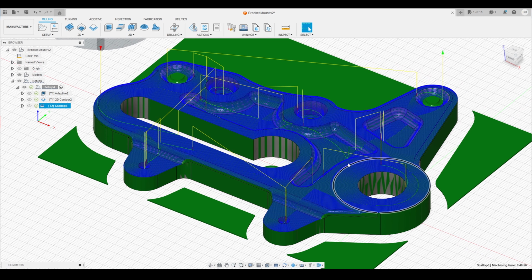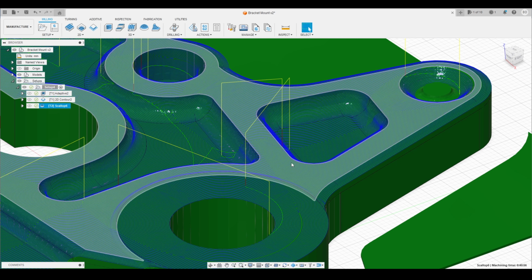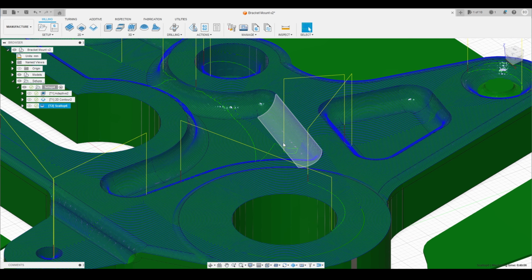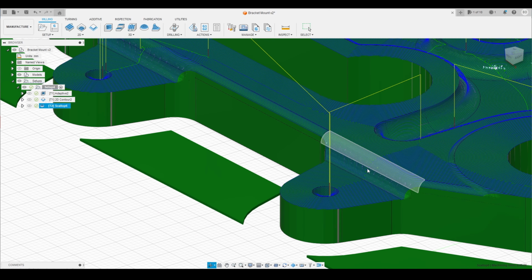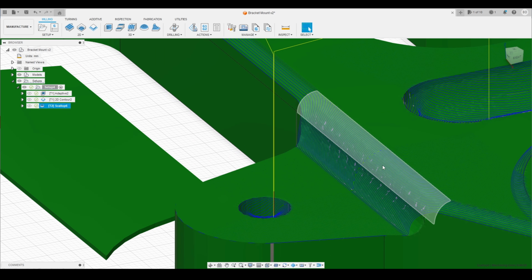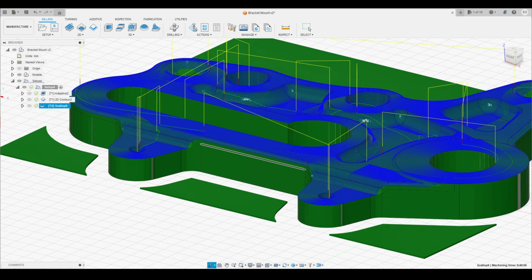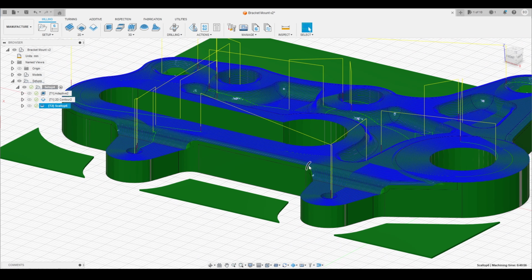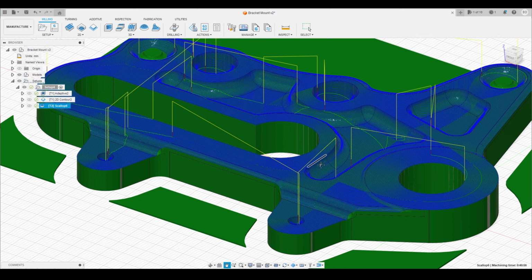And basically it's running a pattern all over the surface of the part, and it's going to mill the faces, the depressions, any interesting geometry. And because we're using a ball nose end mill, we're not going to end up with those sharp edges. We're just going to end up with these little inconceivable cusps, and the tighter our pattern is on the tool step over, the finer the resolution we can achieve. This works really good for creating intricate detail without too many tool changes or a lot of intricate tools.